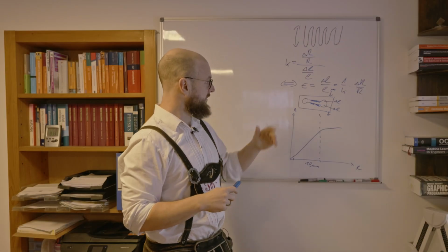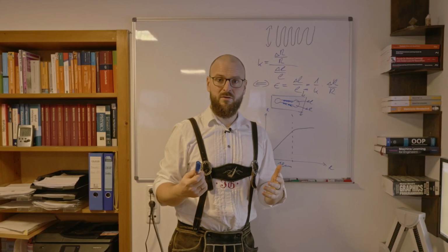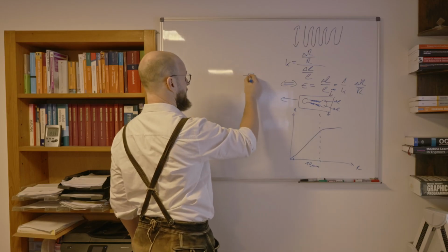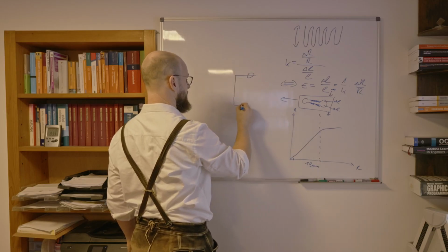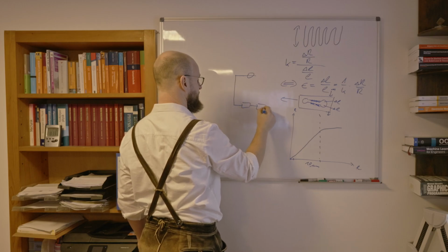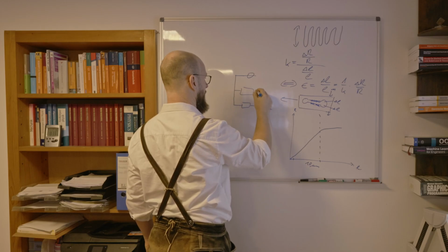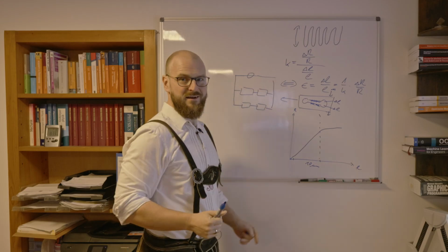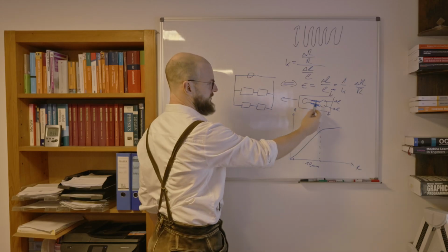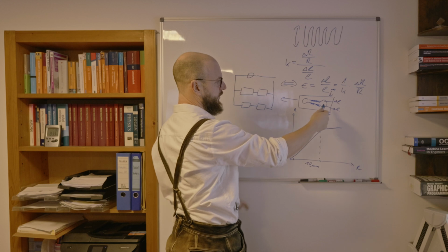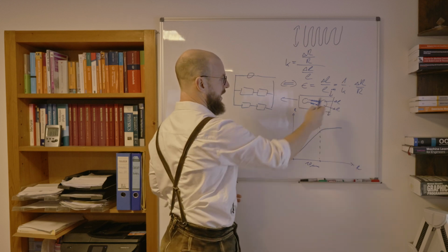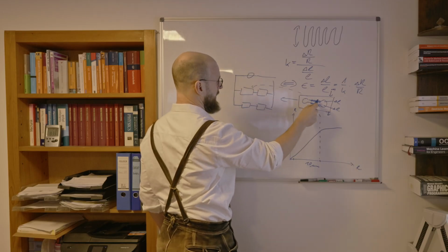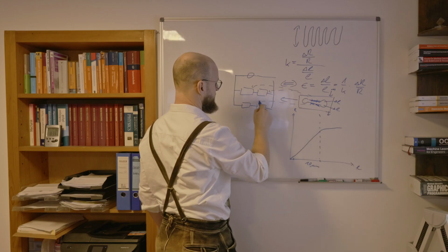Having said so, the last thing to mention is how to measure those resistances, and the typical way is to use those resistance bridges we have already talked about, or I have talked about in some chapters beforehand. Whereas, if possible, 4 strain gauges are placed in a form like this, meaning 2 are elongating and 2 are compressing, and by that building up a full bridge